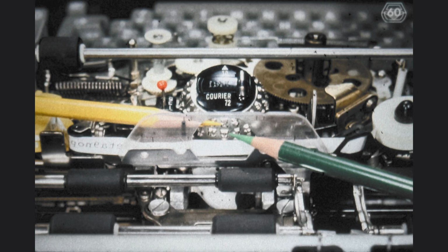When we want to tilt the element so as to print the characters that are in the second band, or belt, on the element from the top, we say that we need one tilt increment. We can say the same thing in other words by stating that at rest, if all we did was cause the element to fly against the platen and print whatever happens to be facing the platen, on an adjusted machine, we would always obtain a Z. The Z is the home position character of the element.